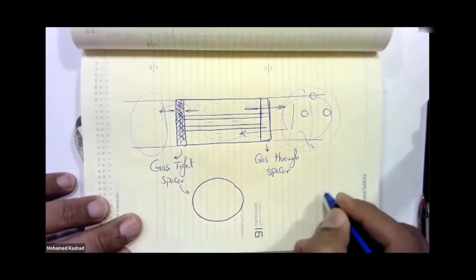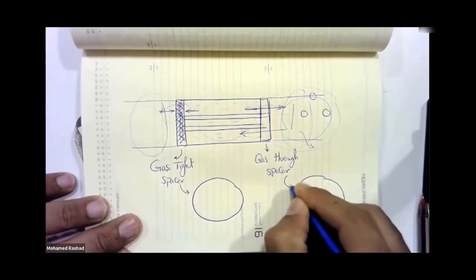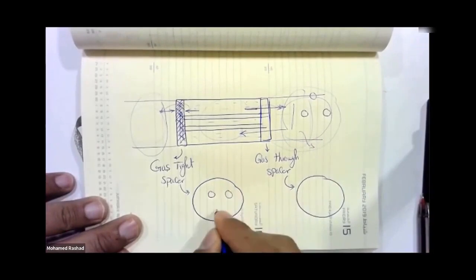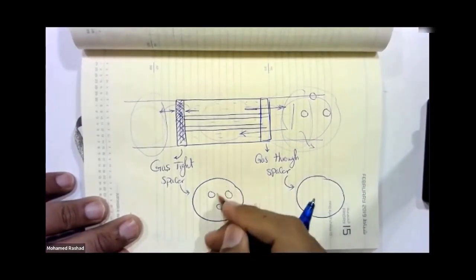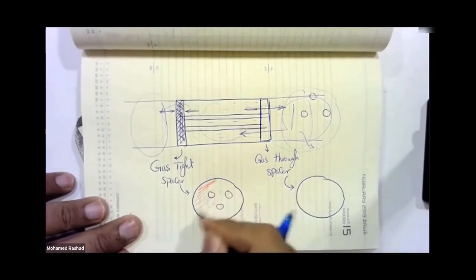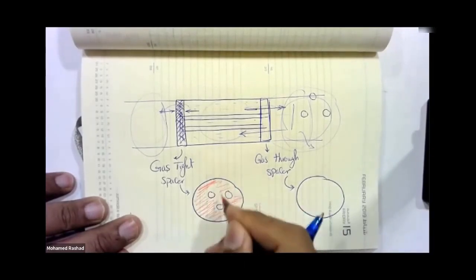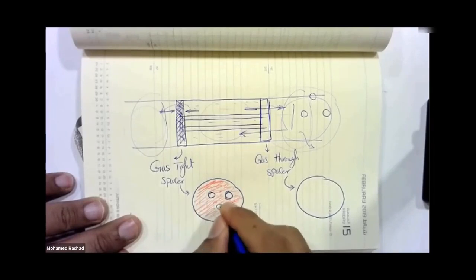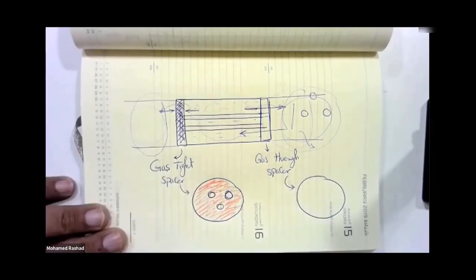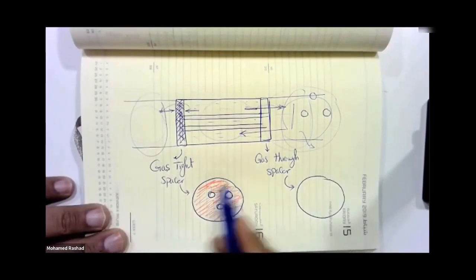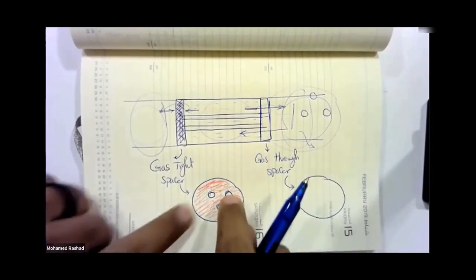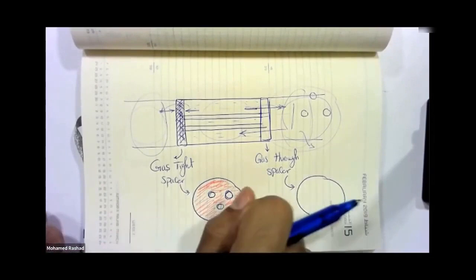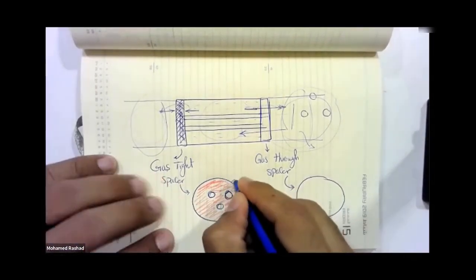If you're talking about a tight spacer device like this, and if you're talking about a through spacer device, it would be like this. For the tight spacer device, I'm talking about something I've seen with my own eyes. You have your three phases here, and the rest of the middle part is all made of something like epoxy as an insulating material. So now it's as if it rests on the epoxy, which is the red part around it. For the gas-through spacer, I definitely can't make this entire area out of insulating material and rest on it.